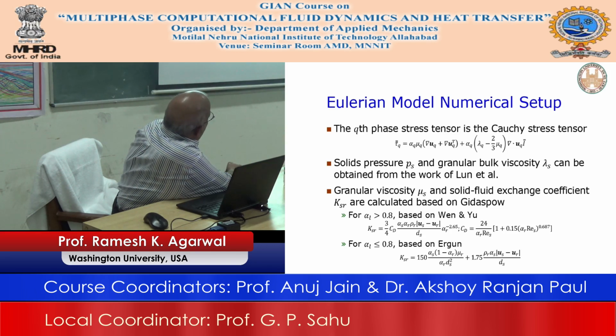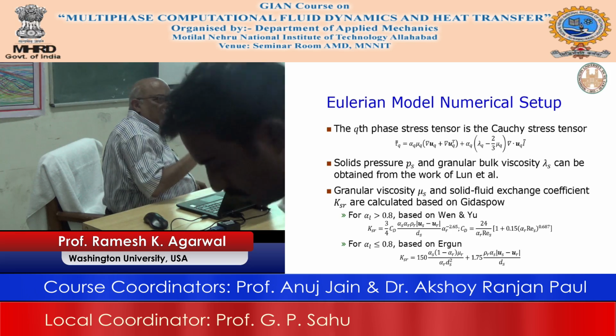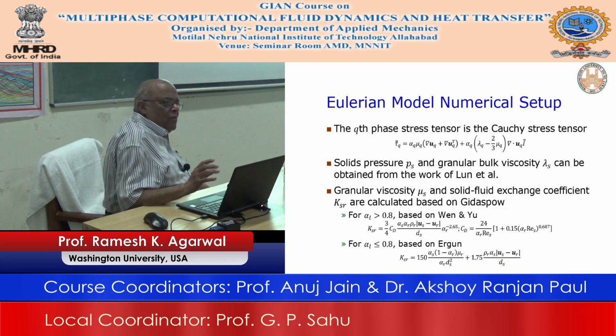And so you have shear stress, and inter-transfer of the momentum between the two phases. So it's a two-way approach. They look complicated, but the whole interface transfer is built into this K_PQ, and they are all in Fluent. The difference now between the DEM and the TFM approach, and also DPM, is what? The equations are the same.